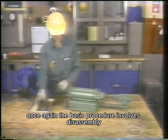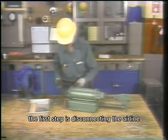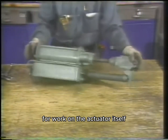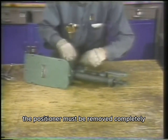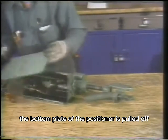Once again, the basic procedure involves disassembly, inspection, and replacement of parts. The first step is disconnecting the air line that connects the pneumatic cylinder to the positioner. For work on the actuator itself, the positioner must be removed completely. The feedback spring is detached. The bottom plate of the positioner is pulled off.